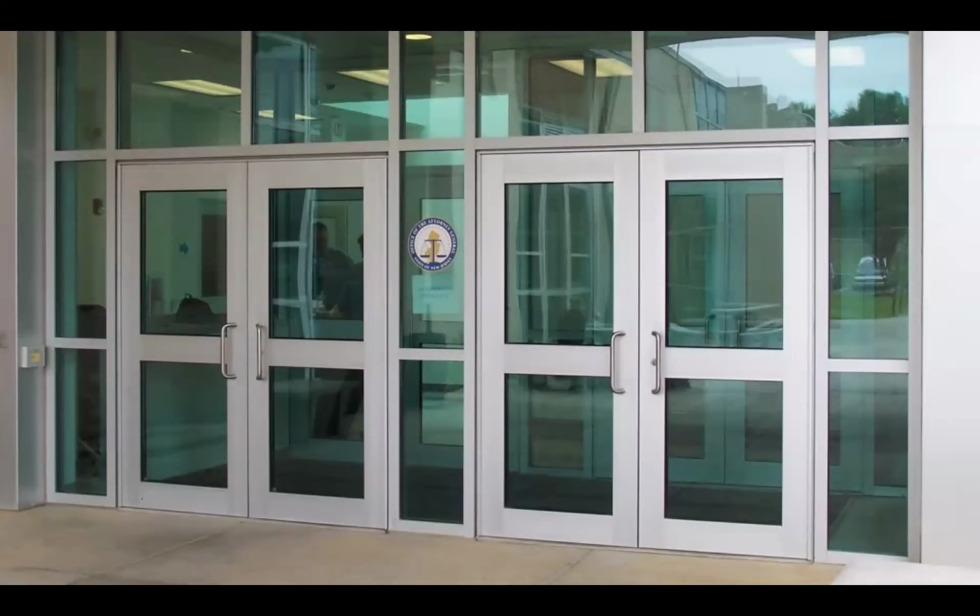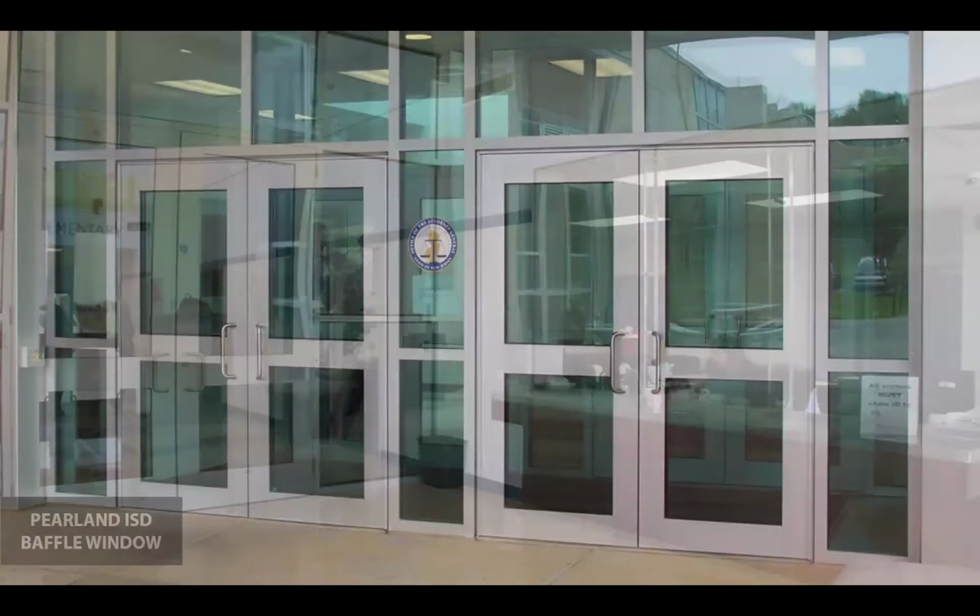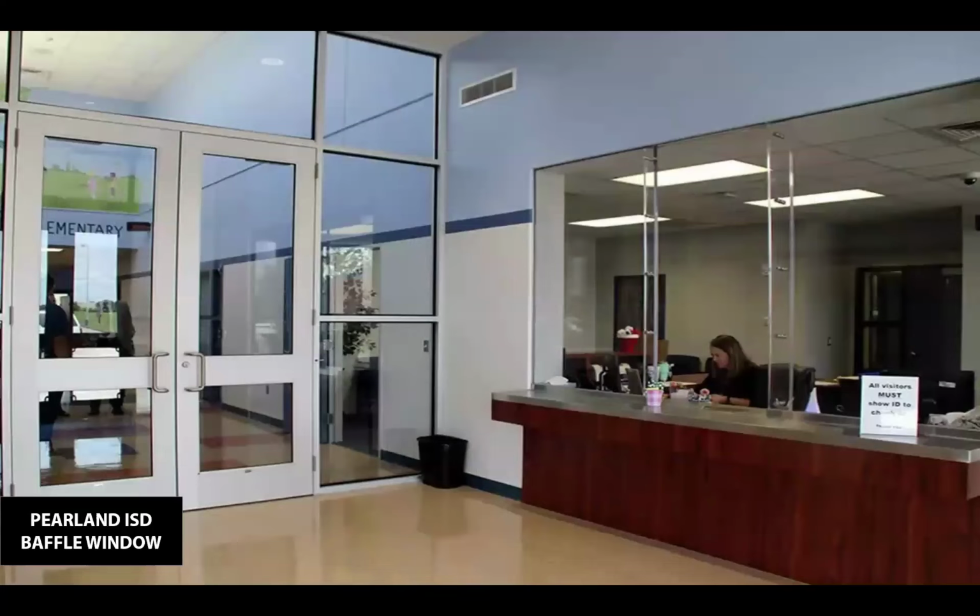That's why it all starts with your design details and your specifications. Just by looking at these two pairs of doors here, this is the police station located in New Jersey with level 5 ballistic rated solutions, but it still has your standard 2.5-inch faceplate, your standard stile and rail doors, and your standard push-pull handlebars as well, hung on continuous hinges. So if anything, you're still achieving everything that you want in the overall building performance in the envelope while still offering security in the fenestration systems from an exterior standpoint.